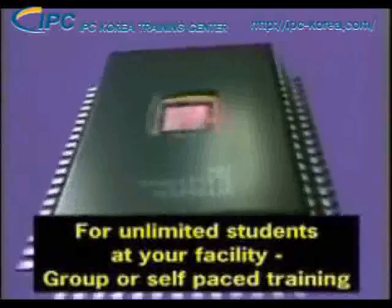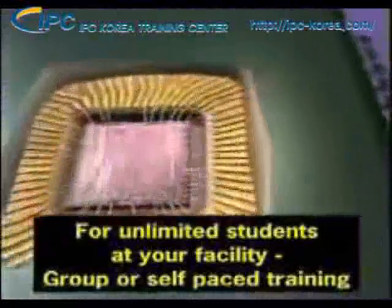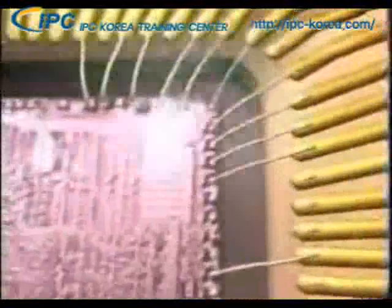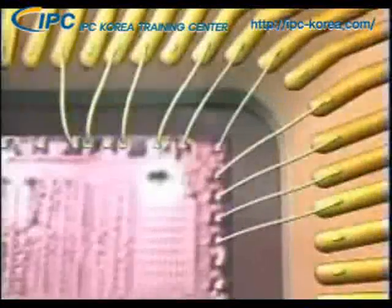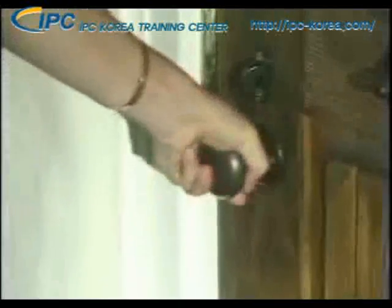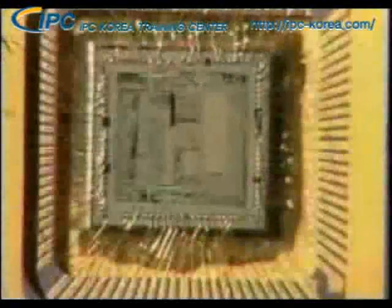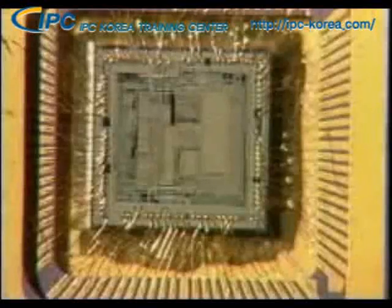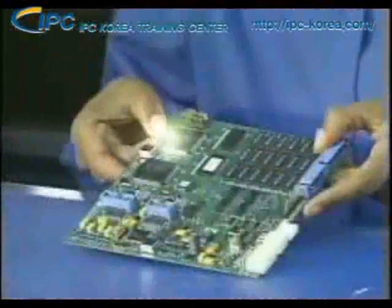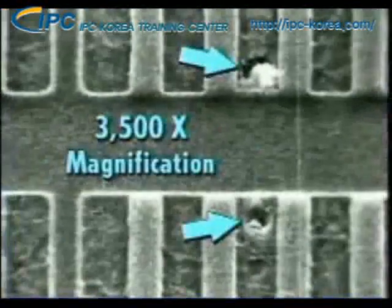The tiny circuit paths in these sensitive devices can be burned up or severed by an ESD voltage so small that our sense of touch can't even detect it. Remember, we can only feel discharges above 2,000 volts, but some ESD-sensitive components can be damaged by voltages less than 20 volts. And you won't even know the damage has occurred, but the destruction will exist inside the component.